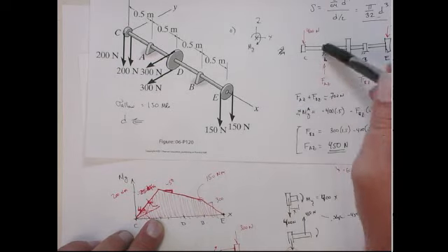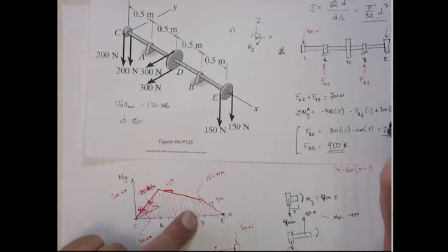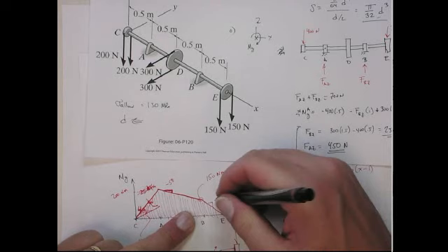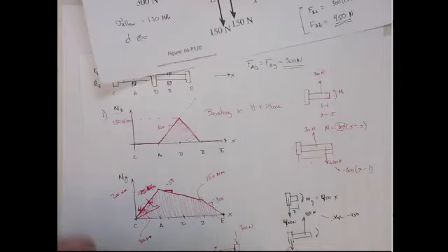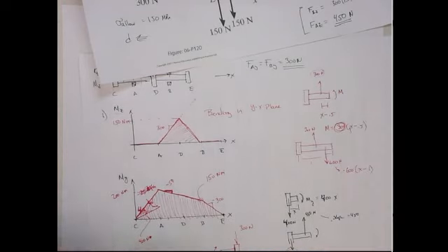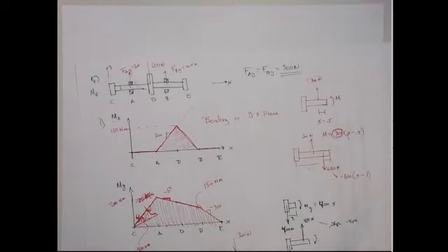The next place you get a point force isn't until B. That point force is 250. So minus 250, minus 50, so that comes down here at a minus 300. Okay? And the reason that works is because when you look at the moment arm, you're always going to have the force multiplied by the moment arm, which is x, minus something else. You'll never get an additional factor in here. So the slope is always going to be equal to the value of the point force. All right. So anyway, now we have the bending moment diagrams.